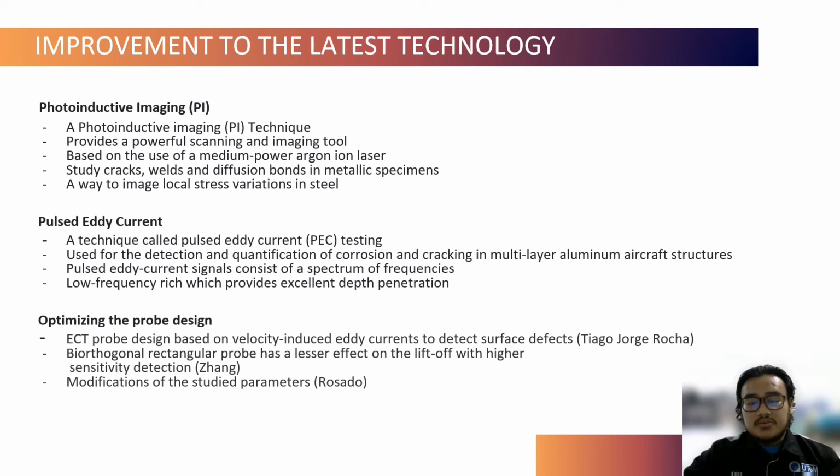Simulation results show the new bi-orthogonal rectangular probe has a lesser effect from lift-off with higher detection sensitivity. Research by Rosado reports the influence of the geometrical parameters of an eddy current planar probe in ECT. The findings showed that modification of the studied parameters could substantially improve the probe performance.